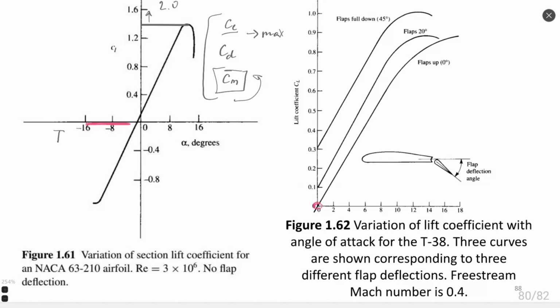For non-symmetric airfoils, and in particular for cambered airfoils, which are curved in some way, zero angle of attack does not result in zero lift coefficient. It can be different. Okay, we can see some similarity between one picture and the other.